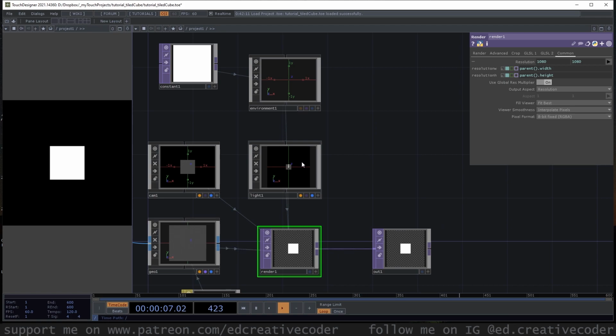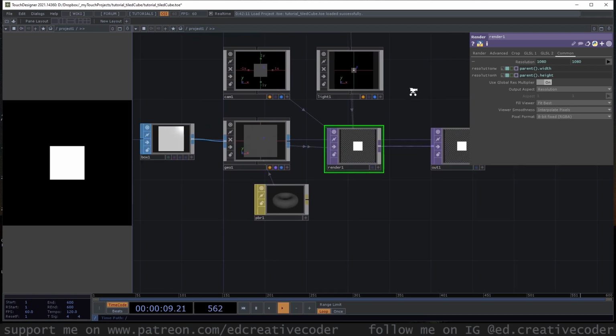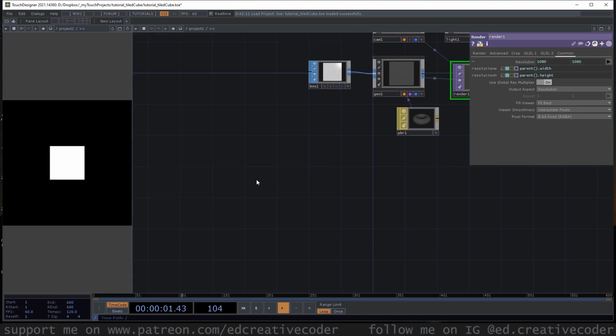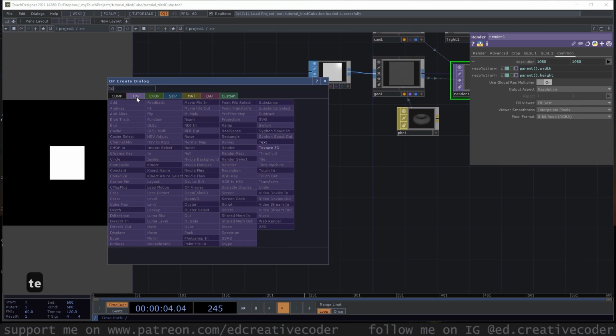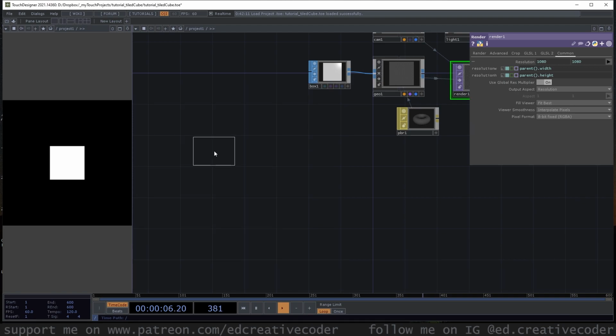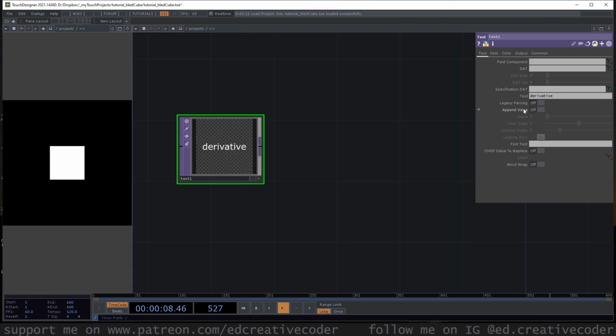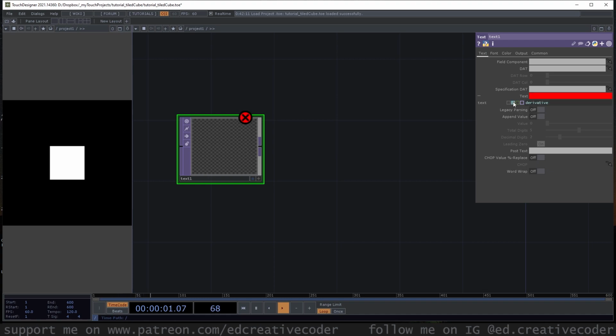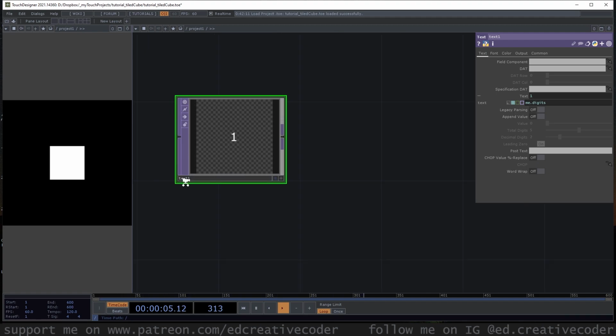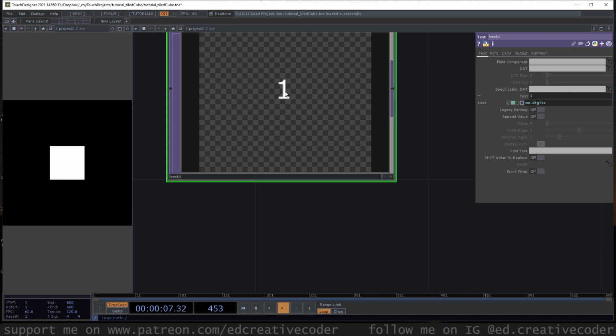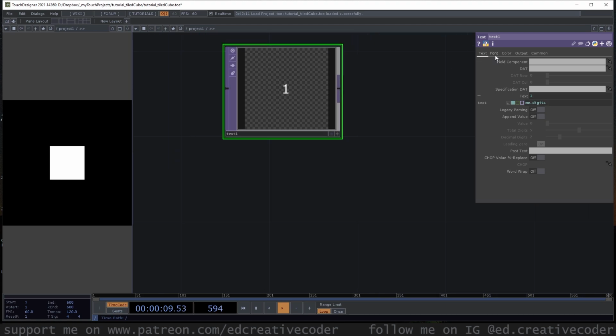Let's go to the main part, textures. Let's make a text top. Go to text, choose the second square, type me.digits. Make sure you choose the second square for expression. So me.digits takes the number from the node's name and puts it here. Let's make it bigger.